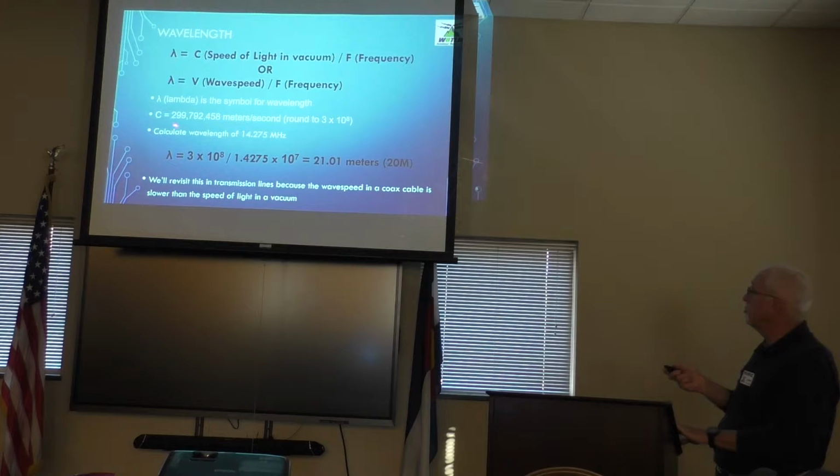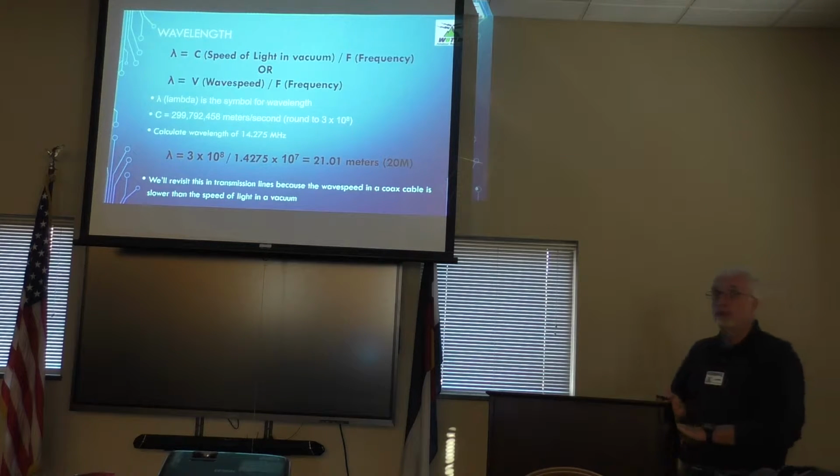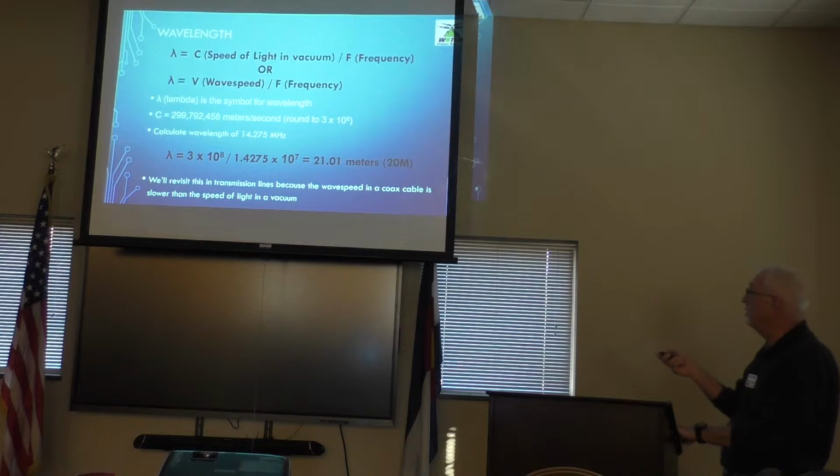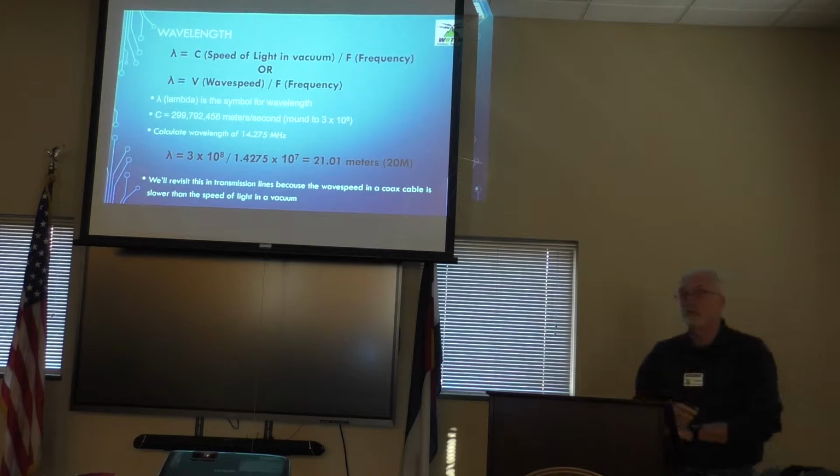So, just for grins, let's calculate the wavelength of 14.275 megahertz. We know that as being in the 20 meter band. Well, we can confirm that. 3 times 10 to the 8th divided by, in engineering notation, 14.275 megahertz, or 1.4 times 10 to the 7th, is 21.01 meters.